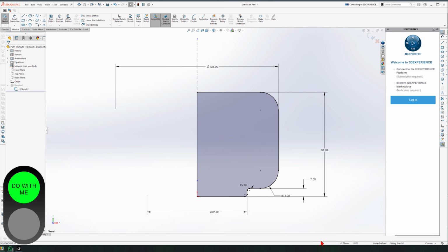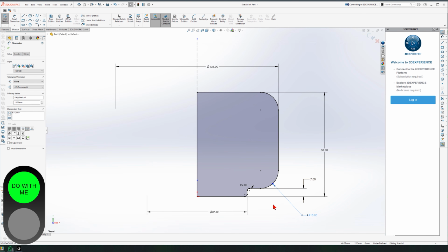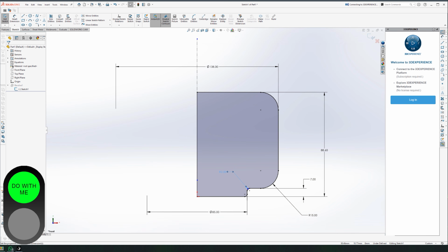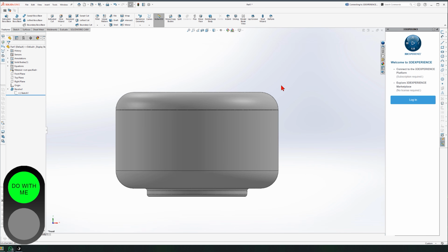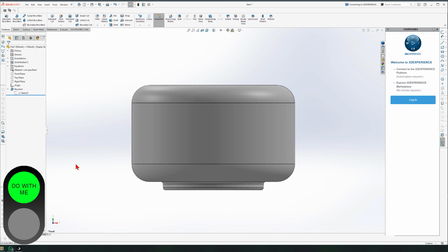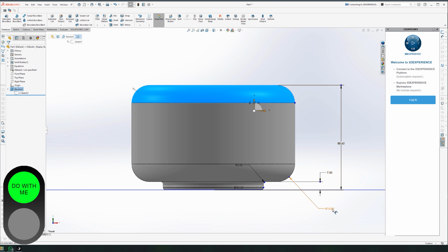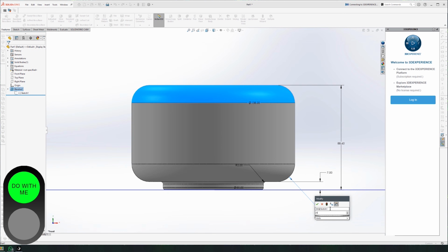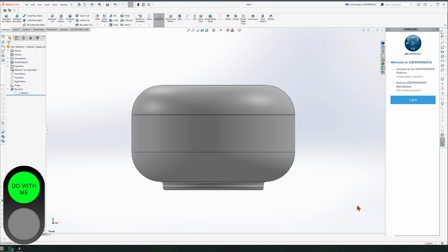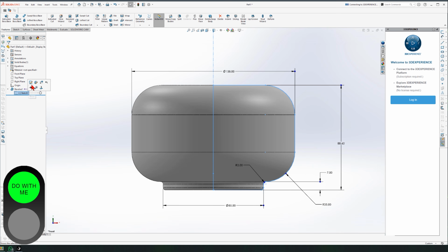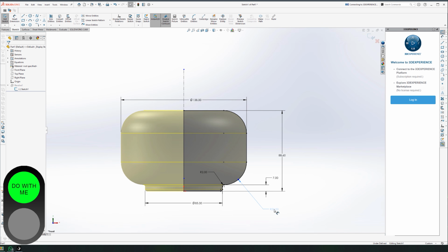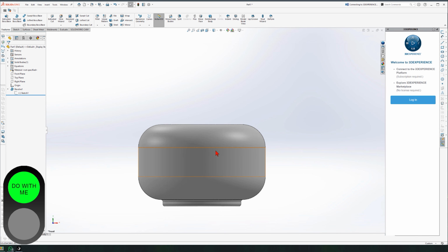Make sure you are on the same page as I am. I just changed the 14 to 7 and changed these 5s to 2. A lot better. Okay. Are we ready? We can continue. I think this is also too small. The radius 15, let's double click on that and change it to 25. Something like this. I just edited the sketch, changed the radius 15 to radius 25. Everything is fully defined, and we're good.